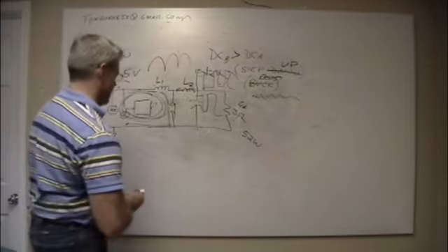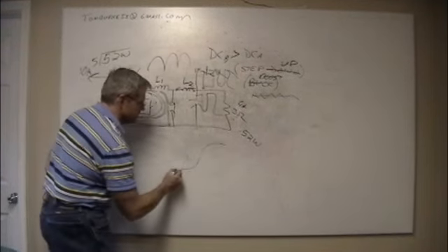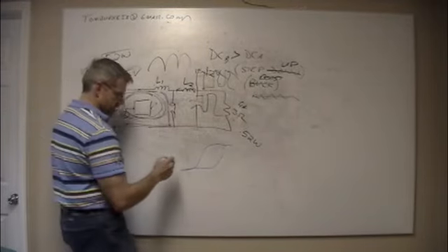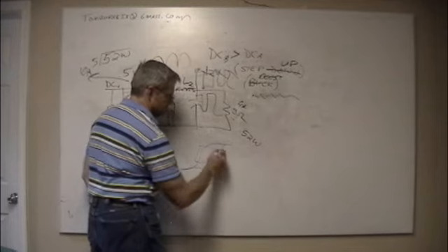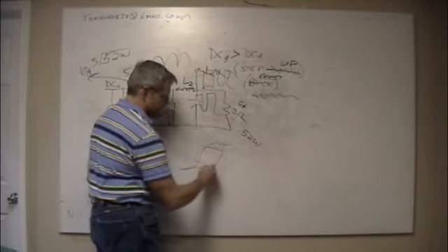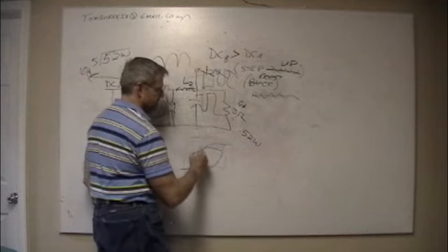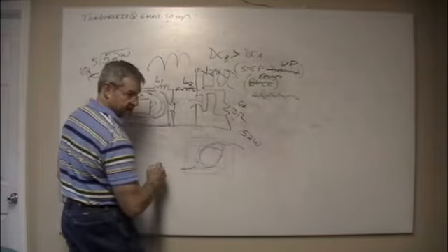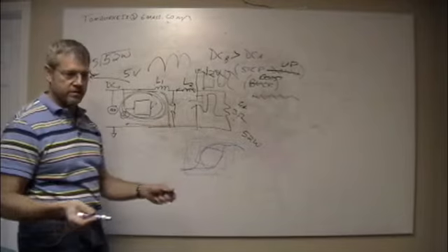And what happens is the magnetic hysteresis looks like this. As long as you're staying in this area, it's not a problem. You come up and you switch back, and you switch back, and you switch back. But when you get up into here, you're overdriving it, you come out, and then there's this relaxation time before you can come back. And now your signal becomes all choppy and weird.